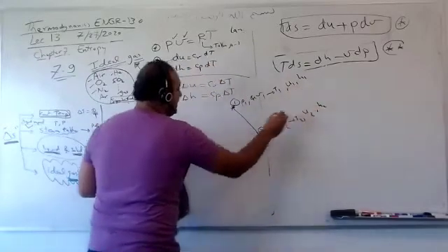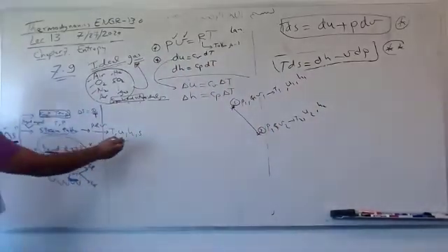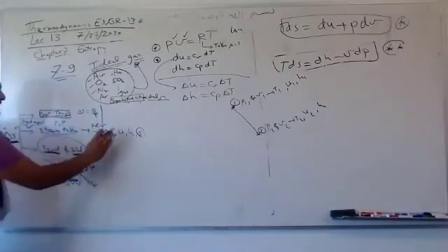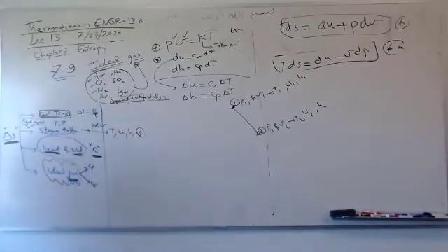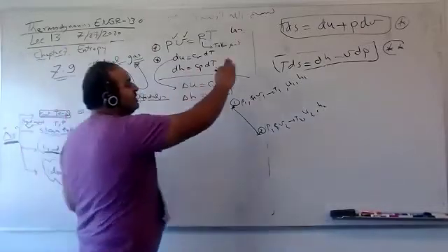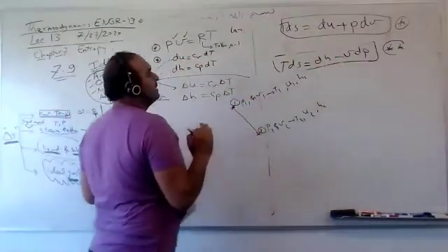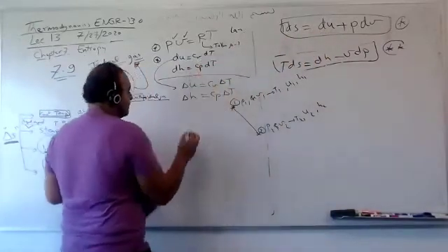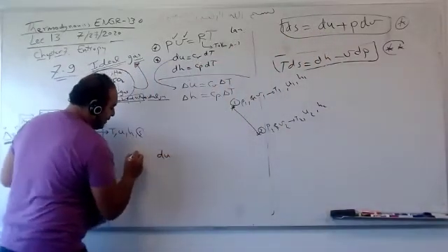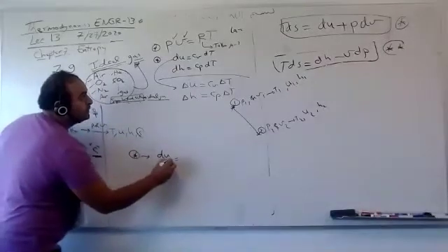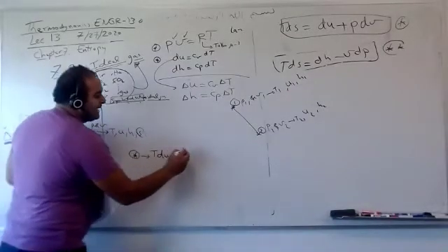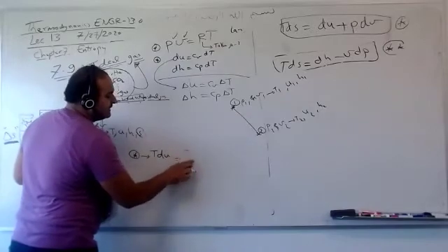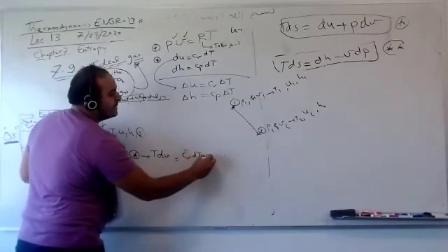How about entropy? That's what we're gonna do now. We learned from the steam table how to get entropy. Now we're gonna learn how to get entropy for ideal gases. That's even better here, because we have this equation or this equation. Plug in delta U equals Cv delta T. So from equation star, T delta S equals T Cv delta T plus P dV.